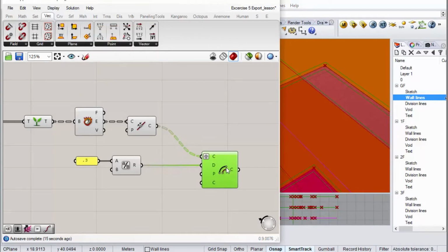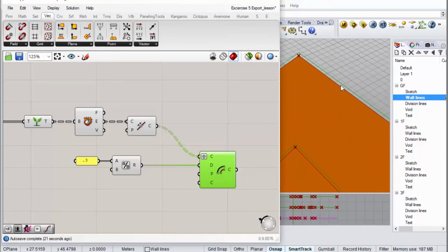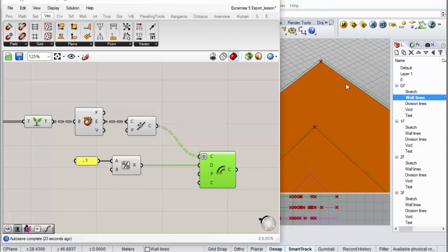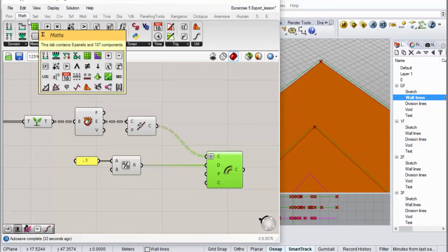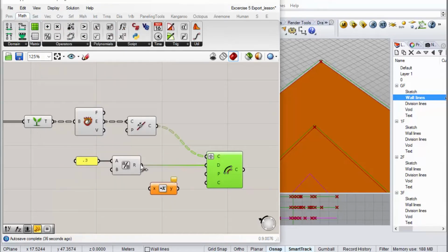Because the thing with offset is that you're never really sure which way it's going to offset. So some of them will be offsetting toward the outside, some of them will be offsetting toward the inside. So we're going to do both and then select the interior one. The way that we do both is just use the negative of this value and also introduce that as a distance.